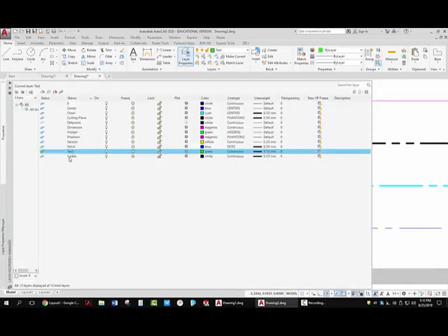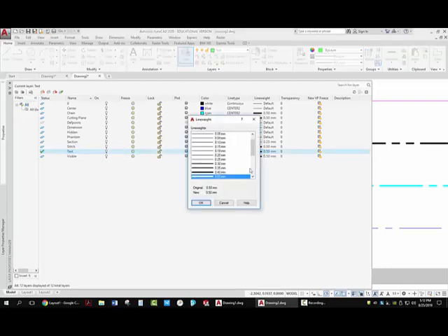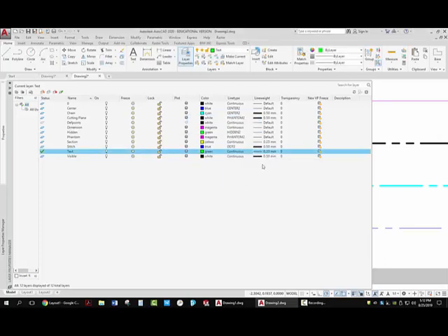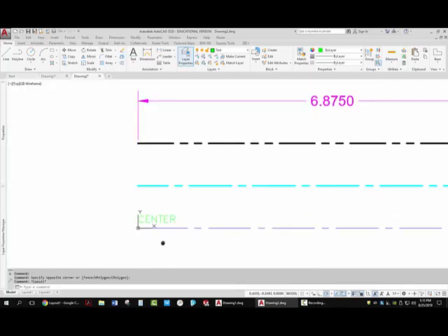I also note, because everything came in so thick, that when I was creating these layers, I made the text layer thick as well, probably because the last layer that I had created was a thick layer, and by going to the new layer command, it just copies the properties of the last layer you created. Now you notice the text looks a little better.